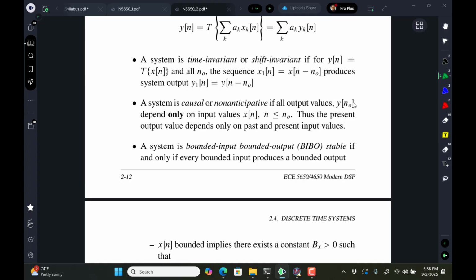In analog electronics, it's hard to make something that's time invariant because components age with time. They might work differently at night when it's cold, differently when it's hot outside. But in a DSP system, you have to purposefully put something into the algorithm to make it time varying. An adaptive filter is an example where you want it to be time varying, and we can do that. We can make it adapt over time, and we'll destroy its time invariance property, but we'll get some desirable property like adaptive noise canceling.